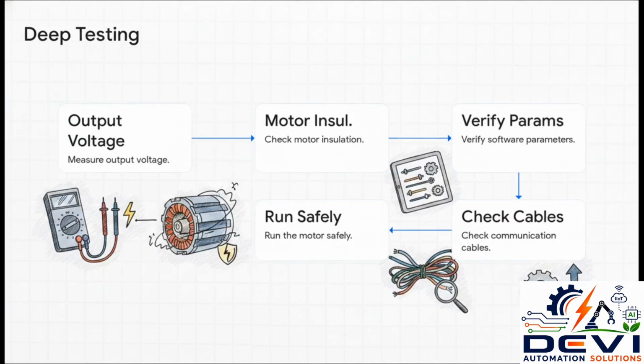Once you've cleared the basics, we move to deep testing and safe running. You'll measure output voltage, check motor insulation, verify parameters, and check communication cables. And only after all that checks out, you run the motor safely. It's all about building confidence at every single step of the process.